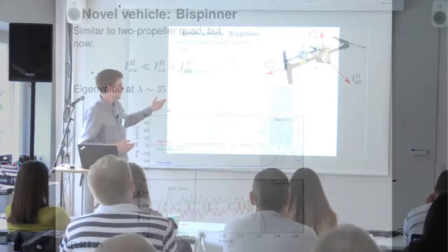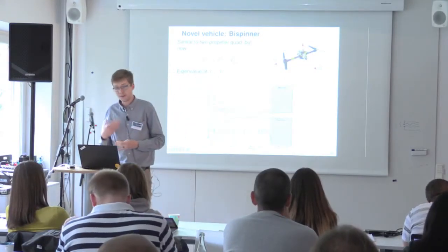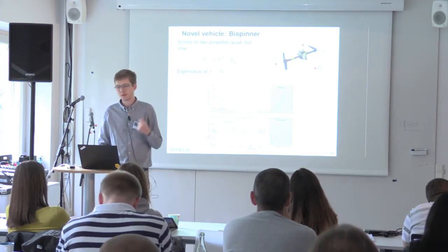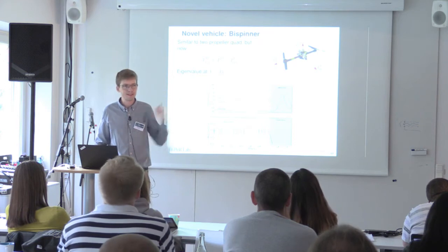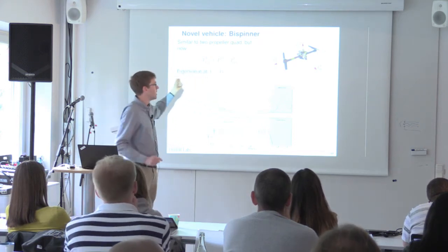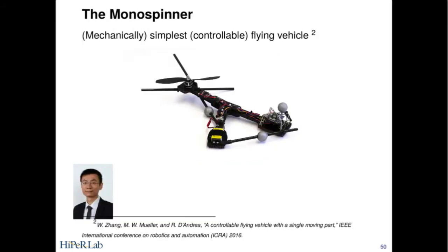And the point here is that if you're not careful about your design, you can end up with something that is very poor and very difficult to control. And this is something that happens often when you design fighter aircraft. You design them on purpose to be unstable, so to have this property, which means that they can react very quickly. But it also means that if your automatic controller does something bad, the system will fail much quicker than you can respond. Right? So you have this instability that you cannot catch as a human, and that just sort of raises the danger level of your system quite a lot.